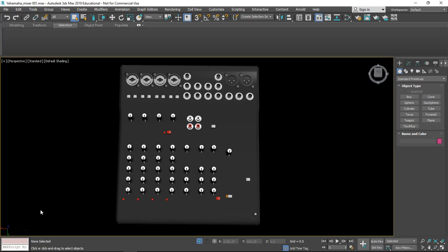Welcome to another video. Here we're going to be talking about the selection tools inside of 3DS Max. First things first, we're going to go to our main toolbar. If we click on our selection regions here, where you might see the marquee, if you click and hold, you get 5 selection region tools. This is because you're selecting a region.